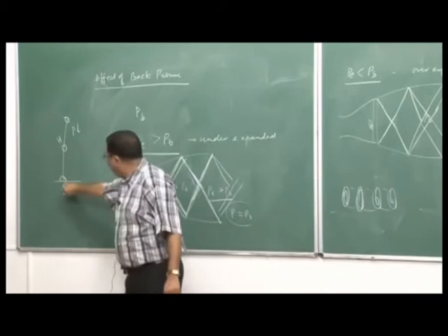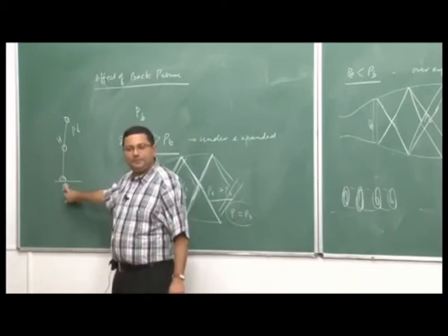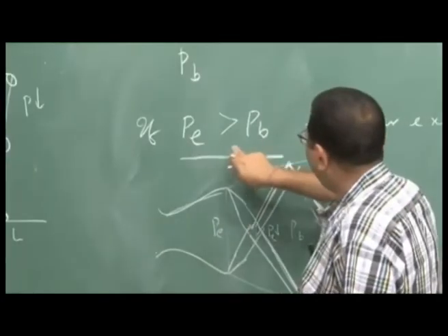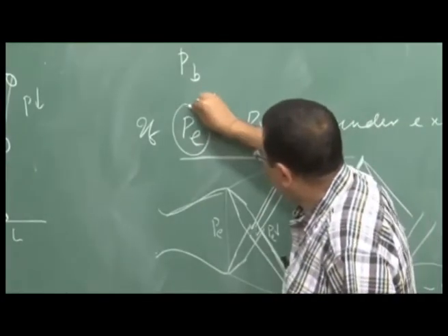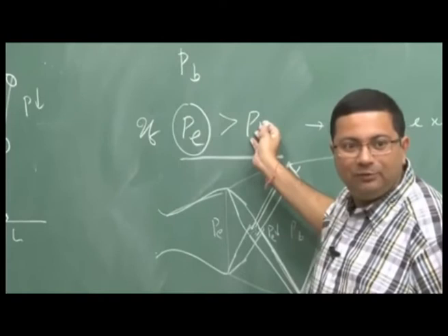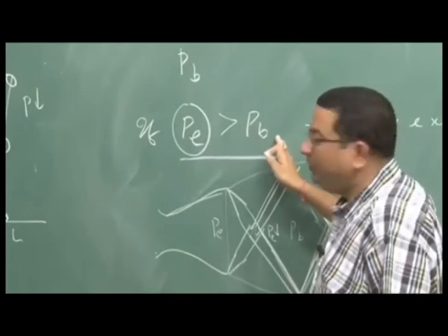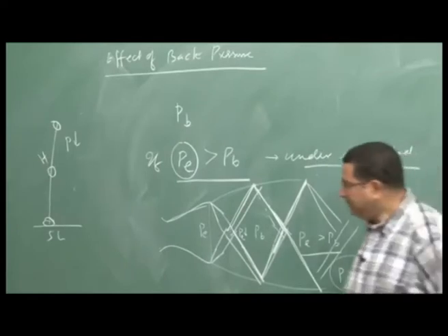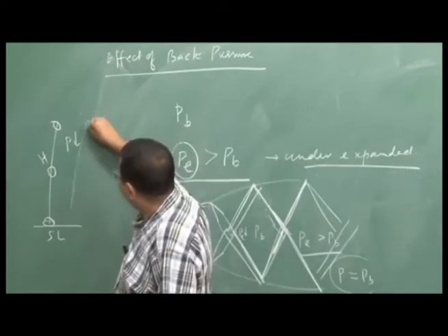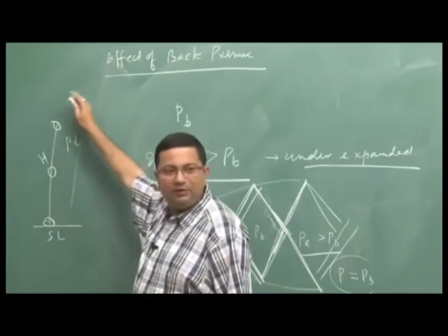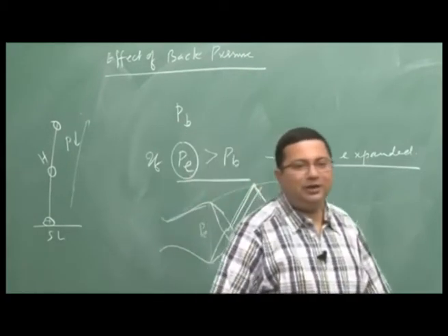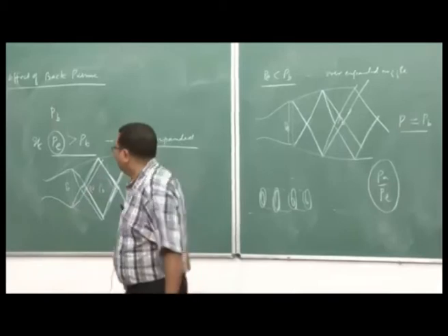If I do it ideal here at the sea level, as it goes up, the exit pressure remains like this, which is our sea level pressure. Now, the ambient pressure is decreasing. So, we have an under expanded nozzle, continuously under expanded. So, the pressure is dropping, we have a continuously under expanded nozzle. So, it will never reach our optimum condition.